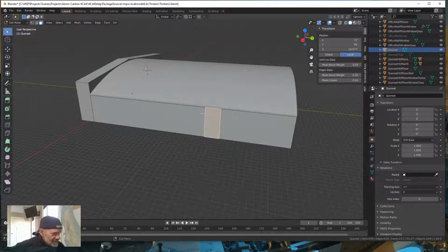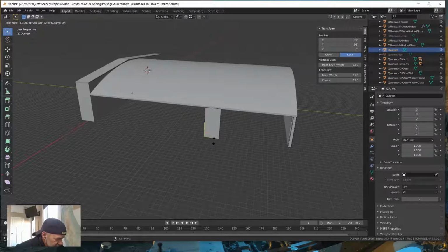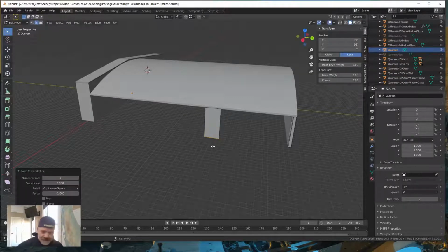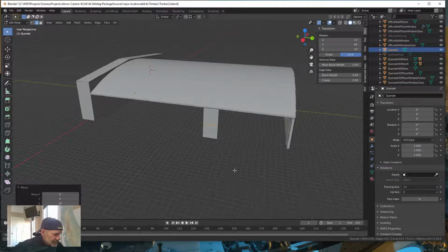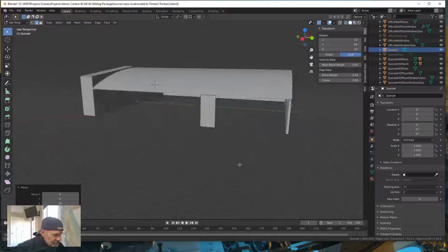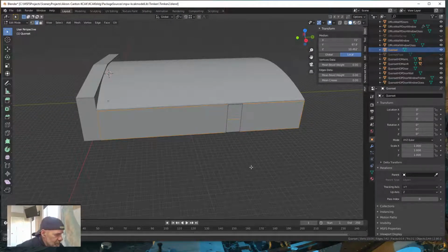Okay, so we're going to isolate this polygon so we can put a horizontal loop cut that's 10 feet off of the floor, right? Alright, so let's select this polygon and H. And then come back to this polygon, Control R, loop cut, click, slide that down to the floor, and GZ 10. Okay, so that's the top of our building, right? I mean, top of our annex. Now we can turn those two walls back on with Alt H.